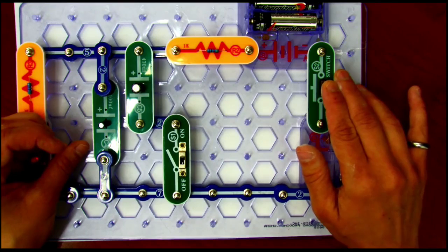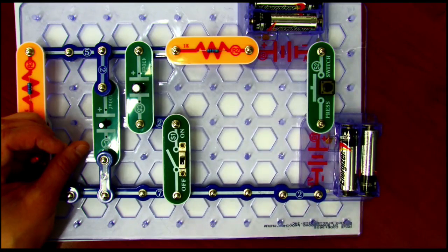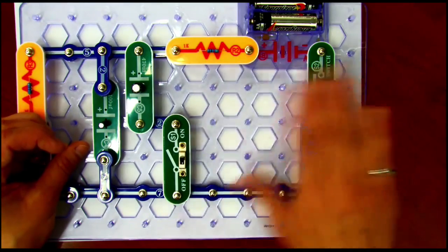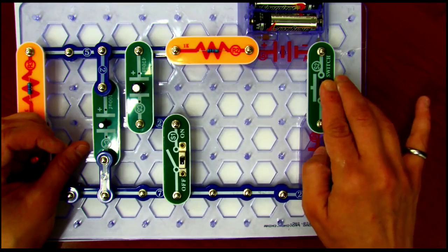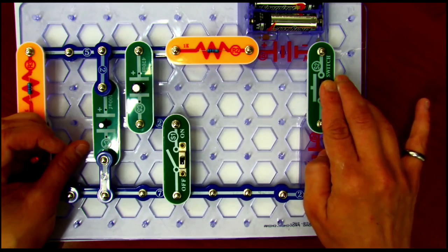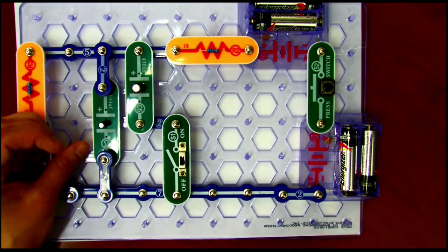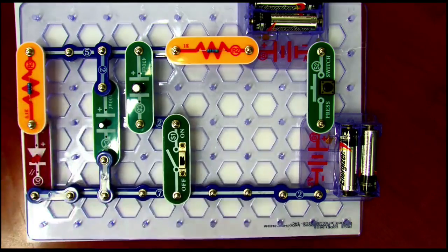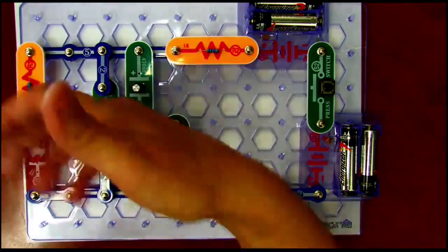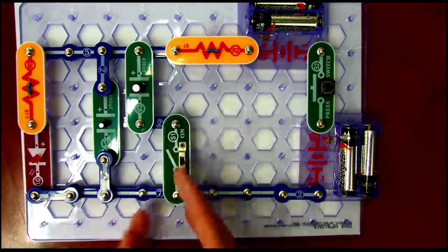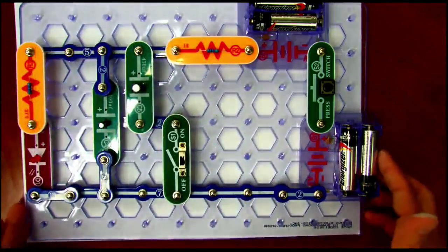We light them up. Now it takes a while for that light to go off. If I switch off that, here, I'll light them up all the way. If I switch off that 470 microfarad capacitor, it'll much more quickly fade away. I'll pass this around, you can play with it, but with capacitors in parallel, if you're stacking up that energy in electric fields to use later on in devices when you're designing things for engineers, you want to stack them in parallel to get that added effect of them.